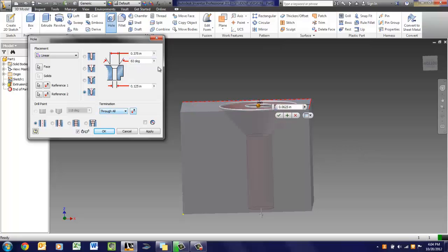And then we also have the countersink. Okay, that gives us an angle. That would be specific to a screw head that would have this type of angled portion on the top. And again, I can adjust the angle. I can adjust the overall outside diameter. I can also adjust the size of the screw itself, the hole that would accommodate a certain screw size. Now this is a lot, I understand.